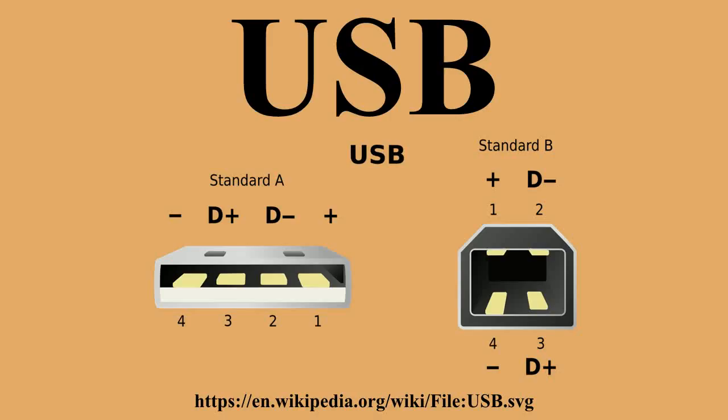Alternate mode dedicates some of the physical wires in the Type-C cable for direct device-to-host transmission of alternate data protocols. The 4 high-speed lanes, 2 sideband pins, and, for dock, detachable device and permanent cable applications, only 2 USB 2.0 pins and 1 configuration pin can be used for alternate mode transmission. The modes are configured using VDMs through the configuration channel.